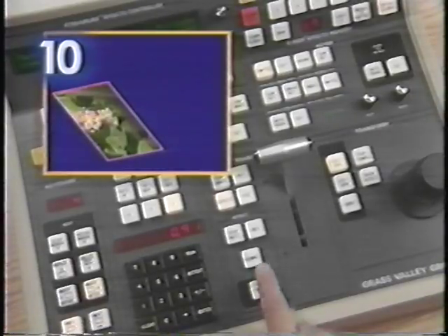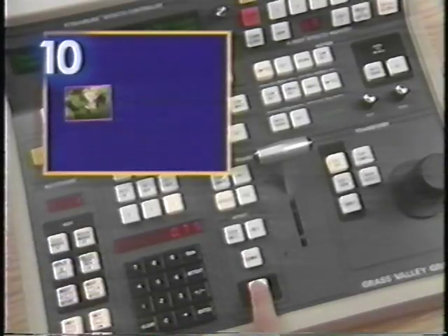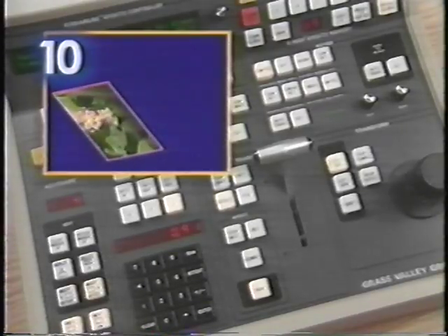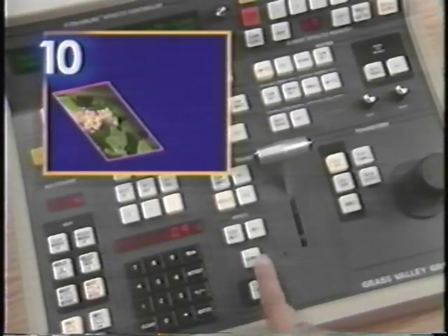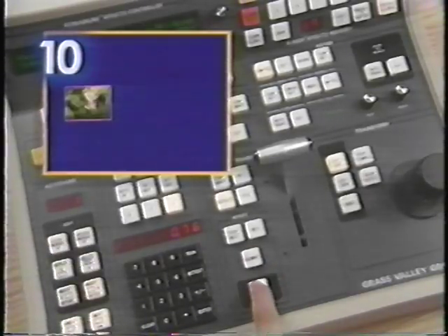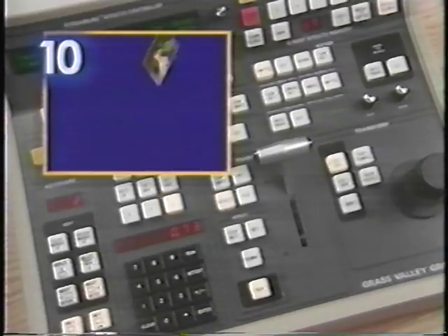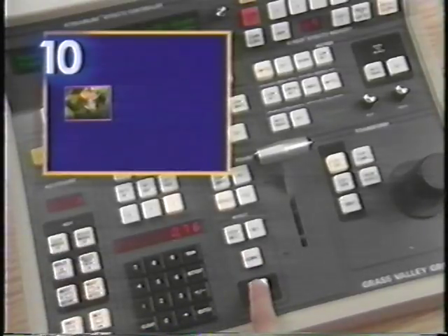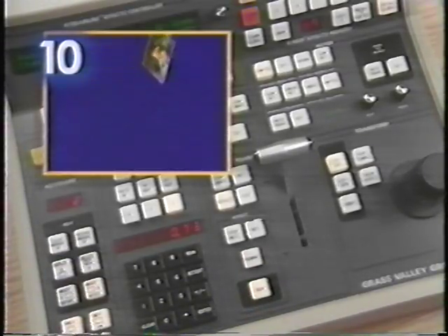That is, there is some spinning between keyframes number 1 and number 2, and between number 3 and number 4. This is because the DPM-100 uses a smooth path function as its default to shape the motion path. The smooth function averages the effects over the entire motion path. You'll learn how to select different path functions in following lessons.